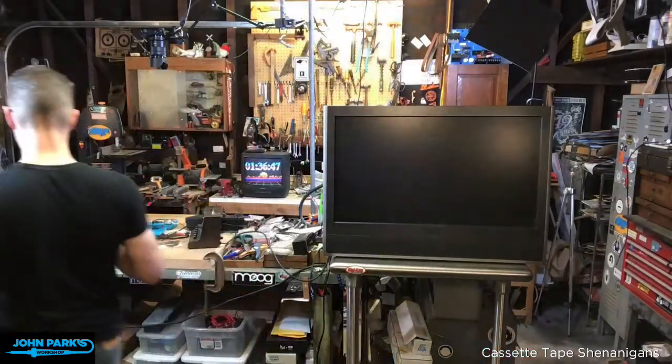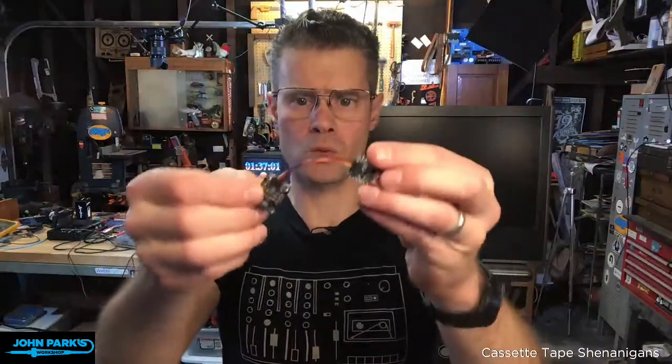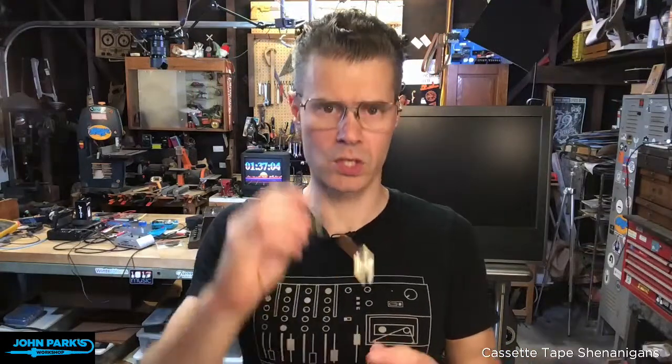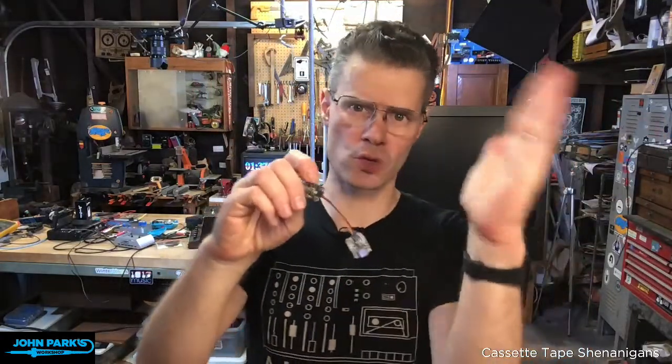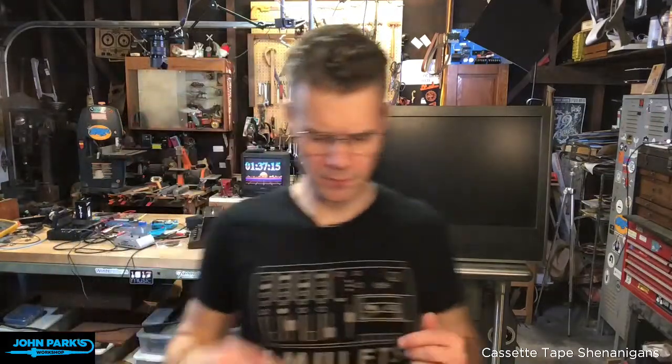So let's see what else. I think the plan with this, next steps will be, I'm going to take my, where did I put it? Take my little digital potentiometer and a CircuitPy, which work great together, and start coding that to be able to just do some sweeps back and forth to change the timing or change the playback of the motor speed. And then look at doing some MIDI input. So it'd be kind of cool to send MIDI notes to the CircuitPy over USB, which it then converts to different values for that potentiometer so that it plays back at different speeds.